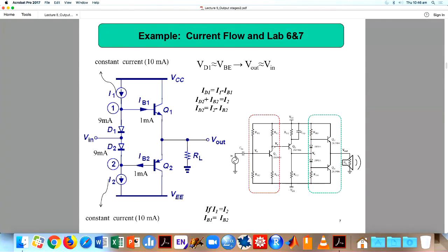Then maybe tomorrow your friend will ask, this is a multi-stage amplifier, why do you need 3 stages? You will say that here we are doing the voltage amplification. In the last stage, we have to amplify the current so that we get the output stage. It is a push-pull stage. You can explain the working principle. This is an intermediate amplification stage that further amplifies the voltage. Then at the end, we are amplifying the current.